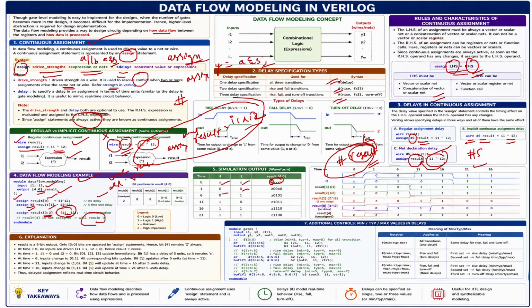You are giving 0, 0, and then I'm getting the output of the XOR gate as 0, and then I1 is output 1. Result 1 is 0, result 2 is any unknown value, because you are giving a delay, right? So that delay is not reflected at the 0th time, that way you are getting an unknown value.